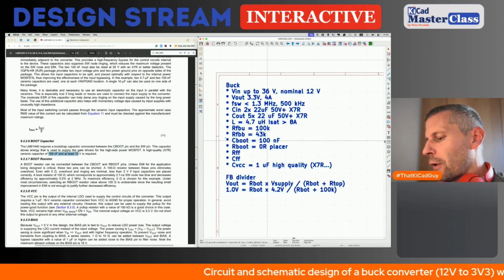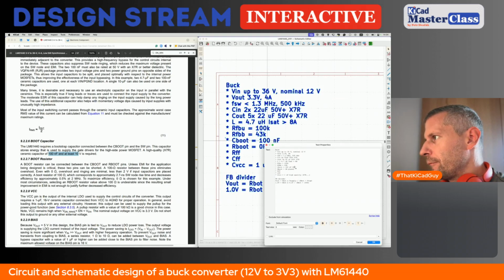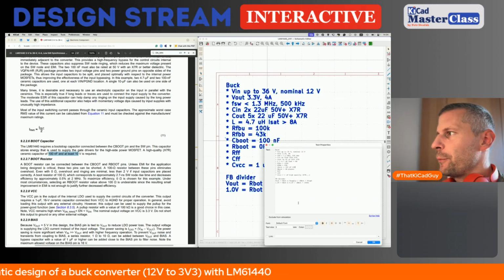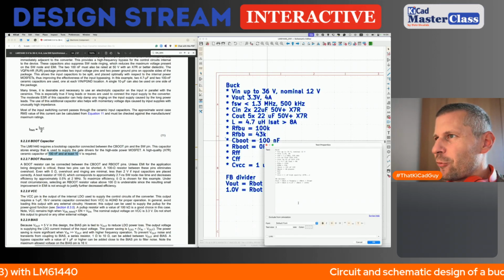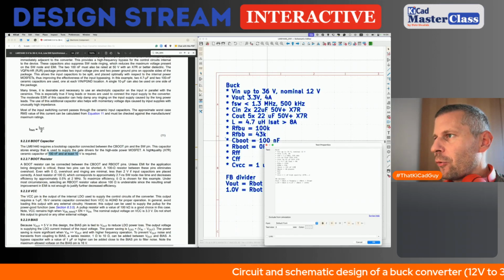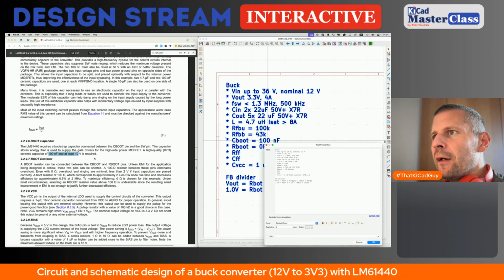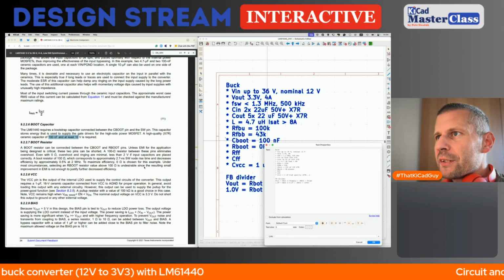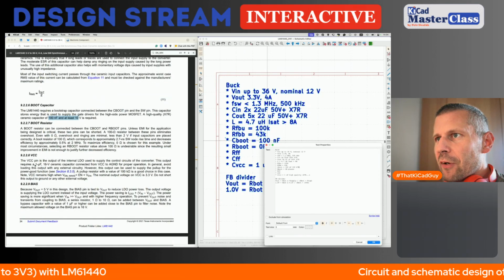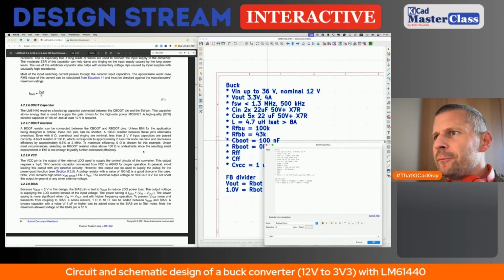Okay, so I'm adding another note. 10 volts will be the minimum rating of the bootstrap capacitor of 100 nanofarads, and they are talking about the high quality X7R. The boot resistor we already found will be a 0 ohm placer. VCC will be 1 microfarad, 16 volts. Okay, I am adding the note about 16 volts.